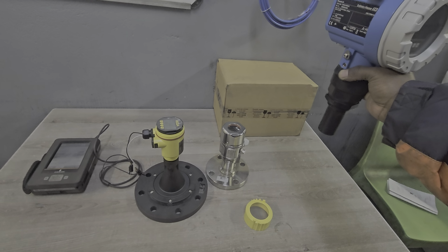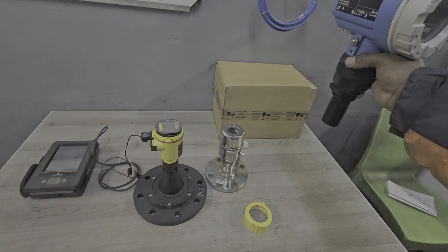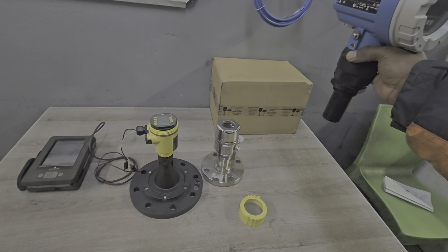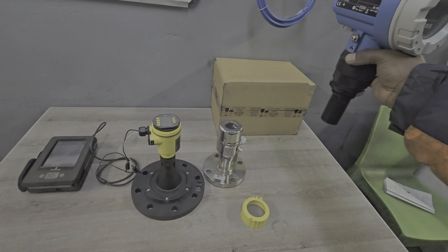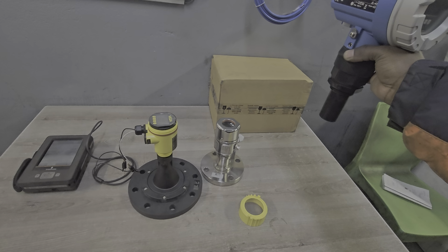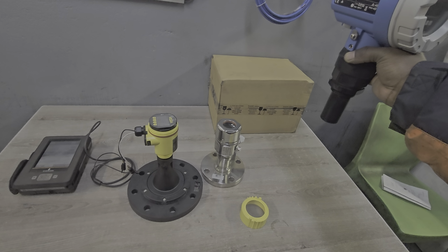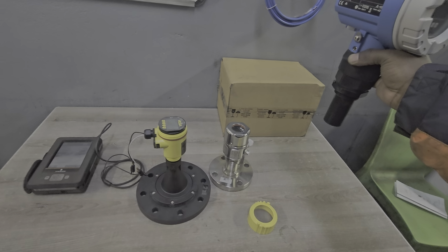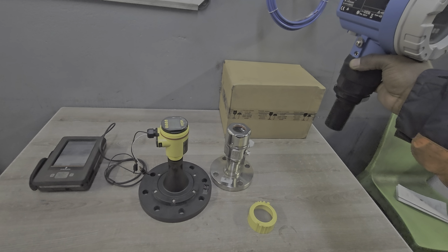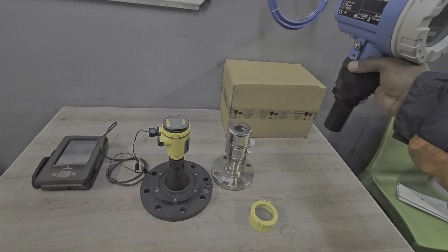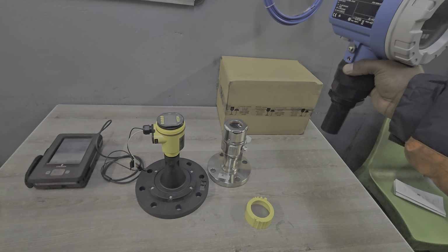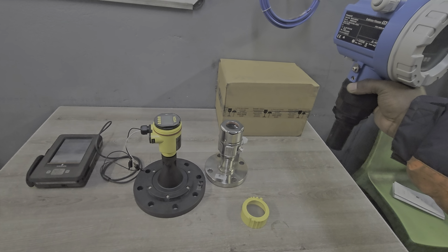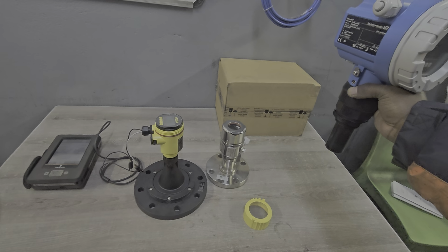So when my vessel is empty, the sound waves will travel from the top of the vessel all the way to the bottom and then come back. So it will take longer. But as the vessel fills up, let's say when it's halfway, the sound waves are going to travel from my instrument to the point where the medium is, the water is halfway, and travel back. So it will take shorter. So we can set up those values and define at what range.